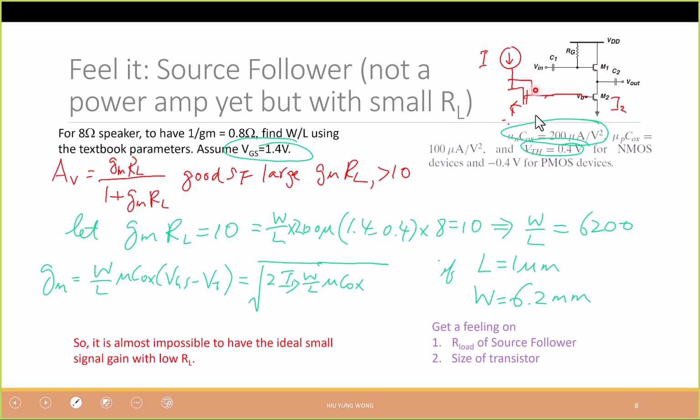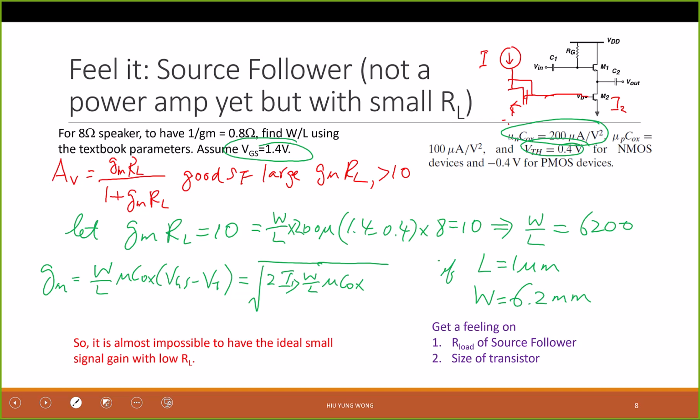But you get confused because now we're talking about copying the current from here to here, right? This one has nothing to do with area. So if this has a unit of 1, this has a unit of 2, then the current will be double. But once you double to here, all this current will flow through M1, right? Do you agree? Just KCL, right? You really need to remember why we can have double, because again, we derived the equation and found that they depend on the area because they have the same gate voltage. That's why it depends on area. But here is different. This is just KCL. Okay, so this is a hint. Don't make a mistake, right? Be very careful.